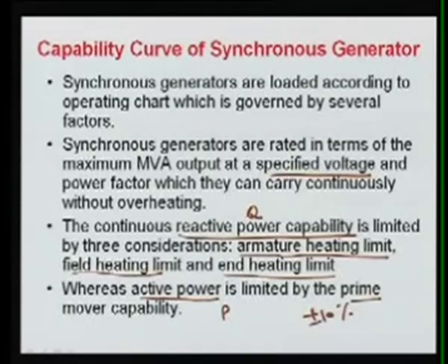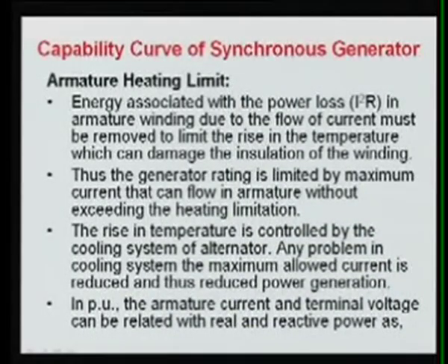Now, let us see all these 3 limits for the reactive power. The reactive power is limited by the turbine capability. Also, we have one more constraint, that is the voltage constraint, which is limited by the insulation of the winding. So the third constraint on reactive power can be analyzed, and we will see the capability curve of a synchronous generator.